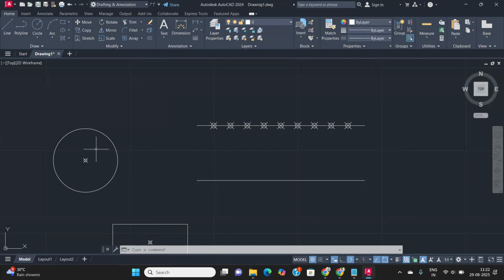If you want to apply this in the circular part, just use divide here also, DIV, and then select the object, and right here is the number of points. Each equal-size segment gets the same point. Once you apply the points, you can make anything else here. Suppose you want to make a circle or a line, you can do it this way. Okay, that's clear.